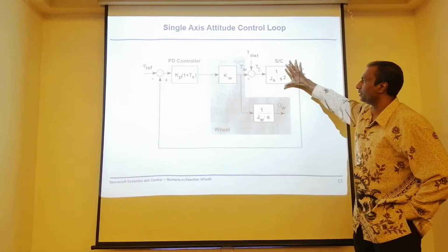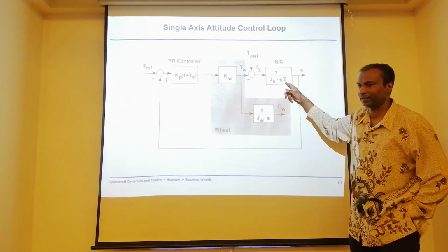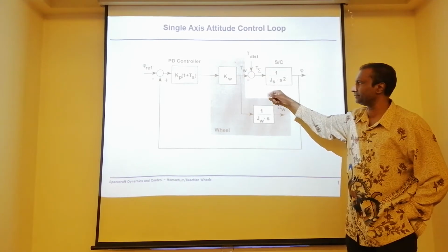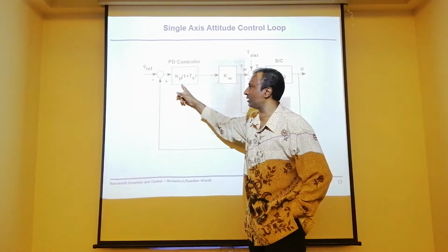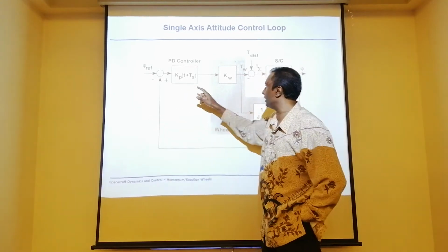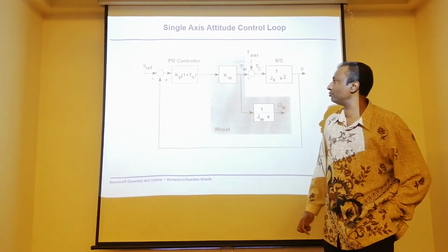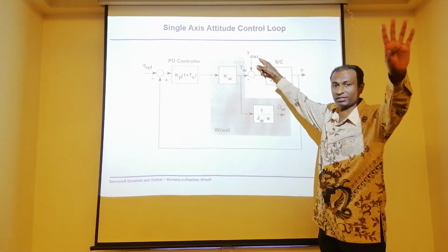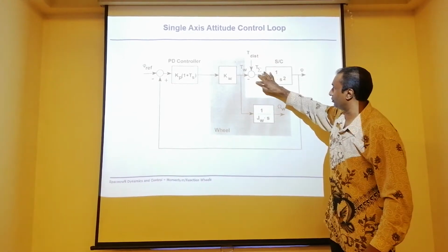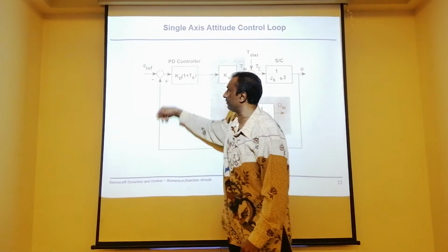Okay. Now, a second order equation, S being the Laplace operator. This is basically the inertia of that satellite, and I use a PD controller. That means I have a proportional gain and a derivative gain. KW is my wheel, the reaction wheel that you use. You have disturbance torque, which you have calculated, and it will come here. The command, total torque, is going to disturb the satellite. I can track back the angle, the reference angle, I can get back here.